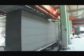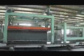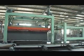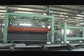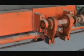Then the trolley stops in the center of vertical cutter. The vertical cutter cuts the cake up and down. While cutting vertically, the cutting steel wire swings like a saw and peels off the skin of cake, in both sides.